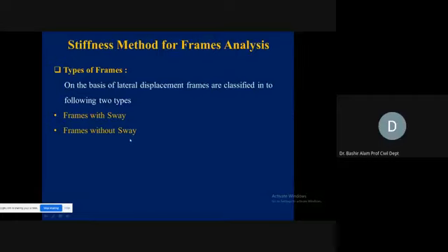Now remember, buckling is a local phenomenon of a member. In lateral instability, the member buckles or displaces laterally, and it is always because of slenderness, when the member is thin. So when you put more axial load, it will bulge sidewise.